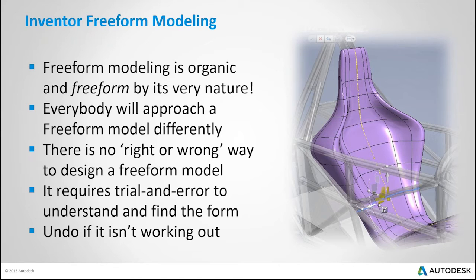There is an undo command as well, so don't forget that. You can see on this little window here, it's not clear in this particular example, it's a bit faded out, but just above the top of the car seat, you can see a little undo arrow, so you can undo within the command itself, or of course you can undo within Inventor as well in the traditional way.